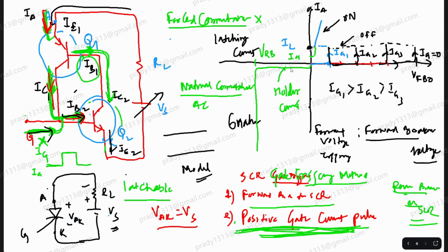Current is between latching and holding while you are turning it off. Is it conducting, not conducting? Conducting, sir. Current is between holding and latching current while you are turning it on. Is it conducting, not conducting? Not conducting, sir.